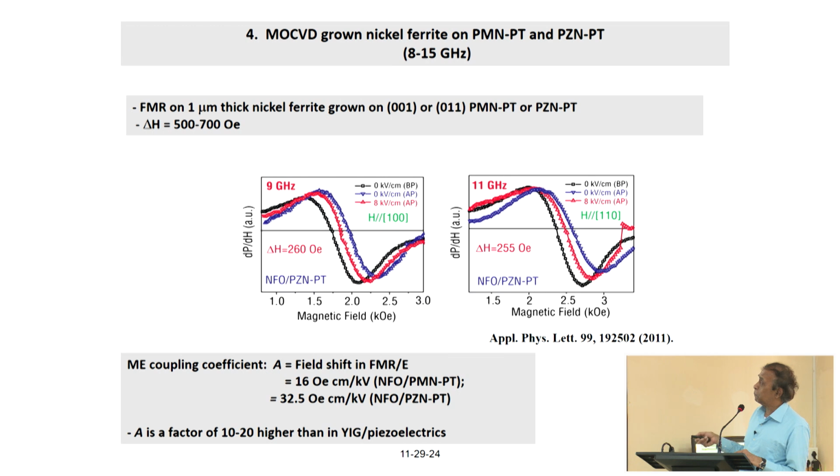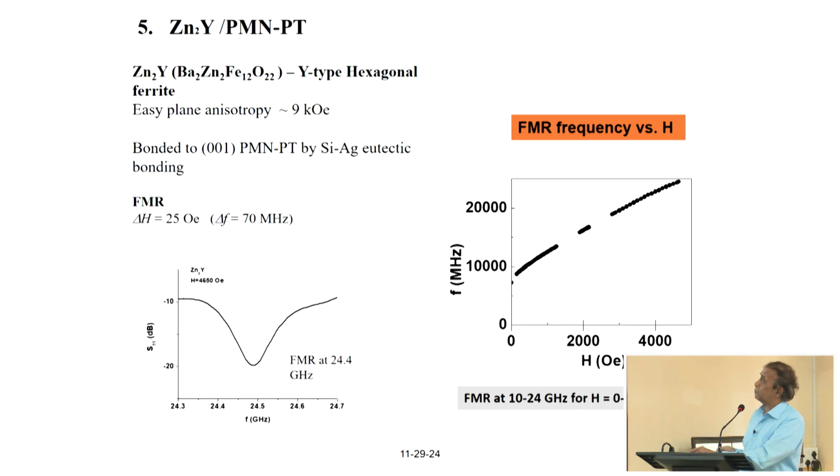And this is on PZT, and the film on PMN-PT had rather poor tunability compared to this. But PZT has a much higher piezoelectric coefficient compared to PMN-PT, but in spite of that, this tuning is no good as far as device application is concerned.